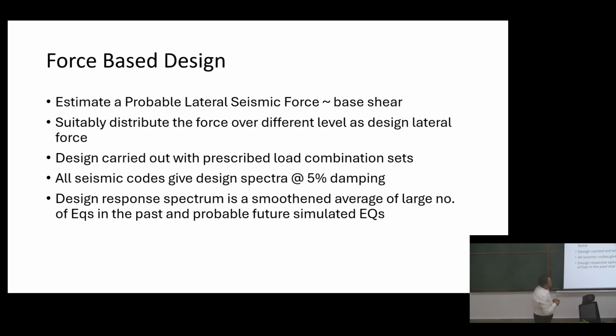And we use a graph which is called the response spectra. And generally all the response spectra are designed or provided with 5% damping inherent to it. If it's more than or less than 5% damping, you have to create a new design spectra. Or you can calculate equivalent viscous damping.